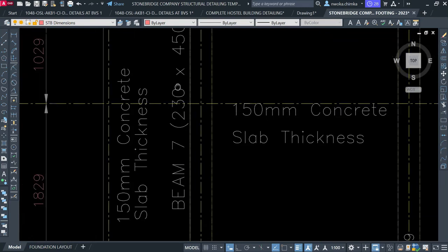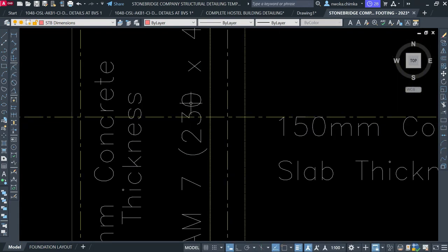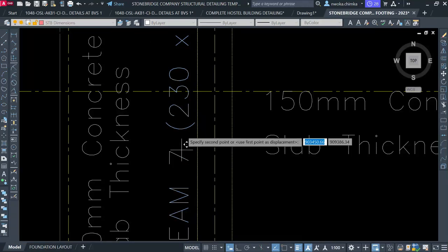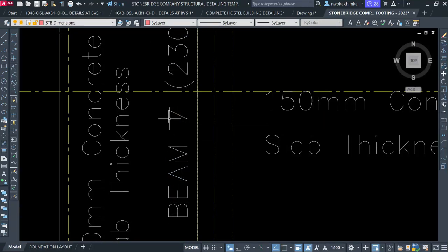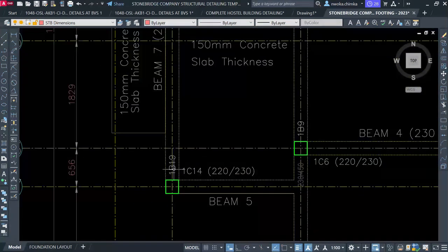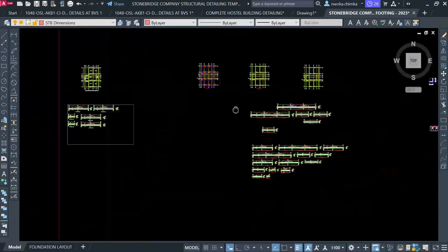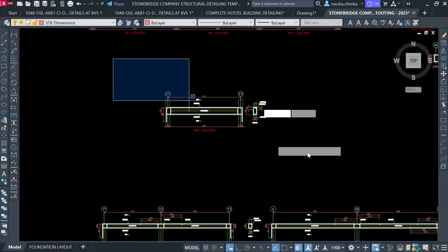So right now we are going to rename beam 19 to be beam 7, as you can see it here. First of all, again, I'll have to remove this text crossing this place, or let me see if there's any space there. Okay, I can choose to make this grid line pass in between this one here directly at this place. Okay, yes, that's fine. So right now we will rename beam 19 to beam 7. I'll go here, locate beam 19 and cut it out to beam 7. This one here, I'll cut it out right now, or move it.